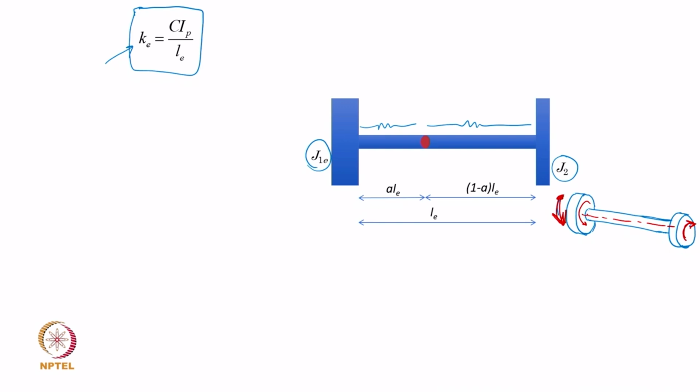And it so happens that, you all have studied in the basic solid mechanics or strength of materials course that there is a location somewhere here along the length where the twist is maximum at the 2 ends and the twist gradually reduces to 0 here, and then the twist is negative in the opposite sense in the remaining part. Okay.